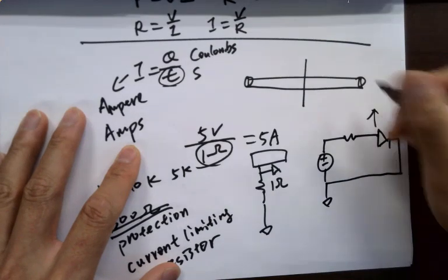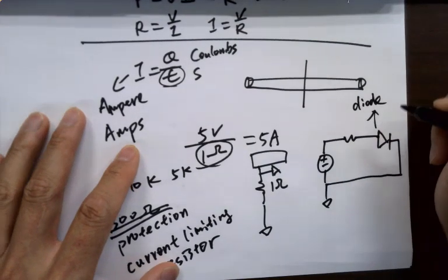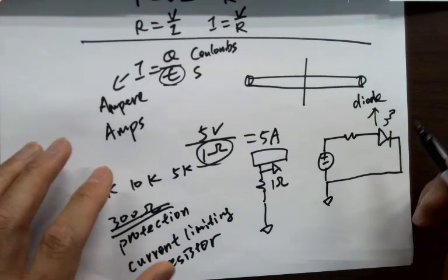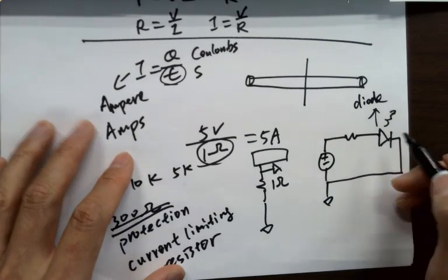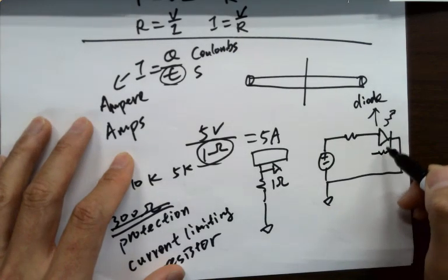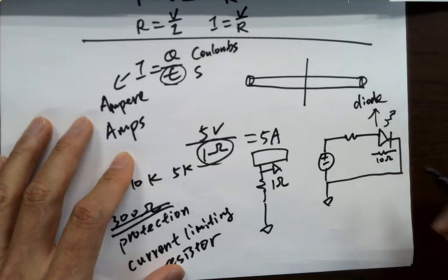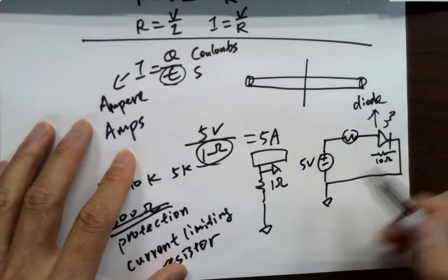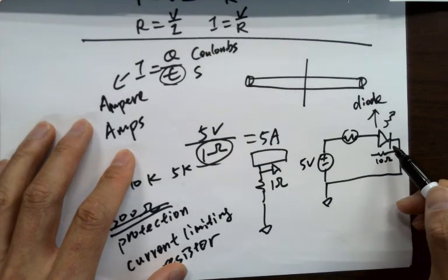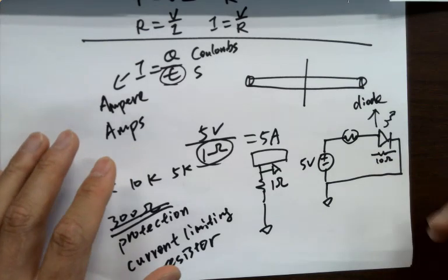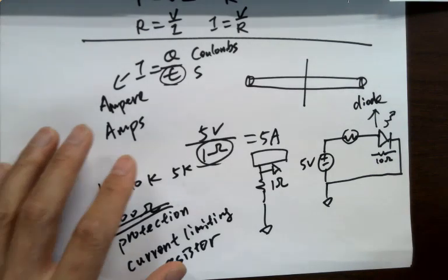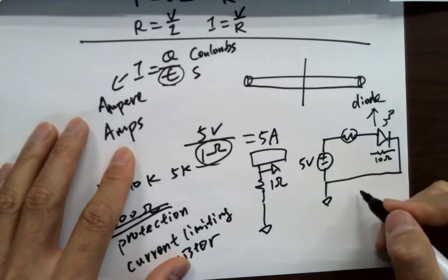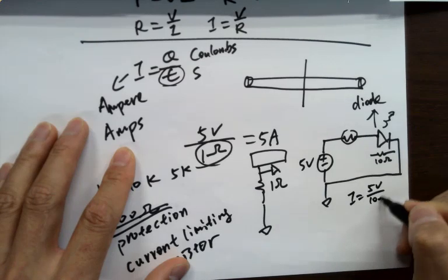So LED is a diode. Light emitting diode. It's going to emit light. You run the current through it, it's going to emit light. Okay? Because the internal resistance of that guy is super low, for example 10 ohms, if you supply this guy with 5 volts without a resistor here, what's the current going to be through it? Now it brings up the terms for you guys to answer. What's that? Half an amp. Is that half an amp? It's going to be I equals 5 volts divided by 10 ohms, right?